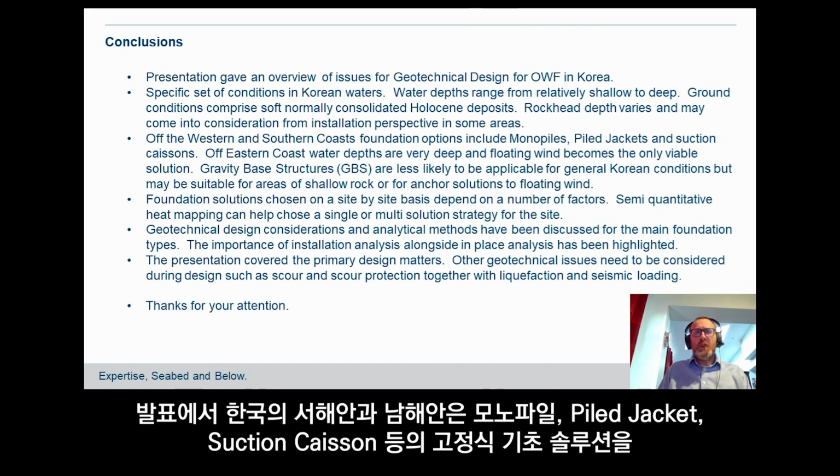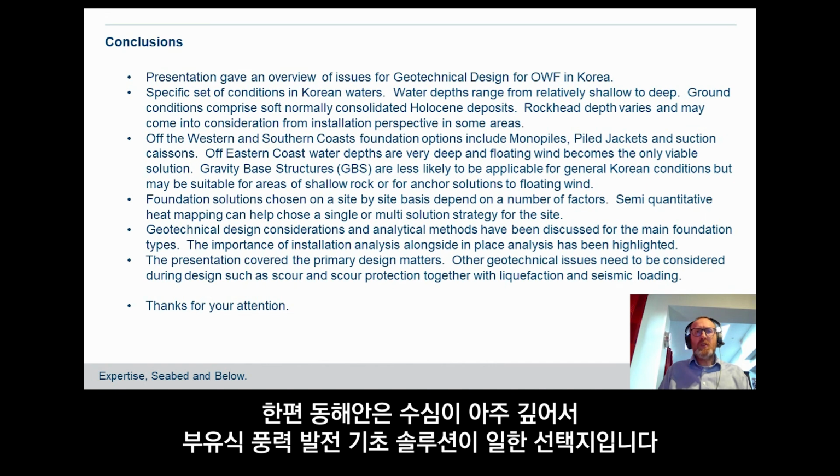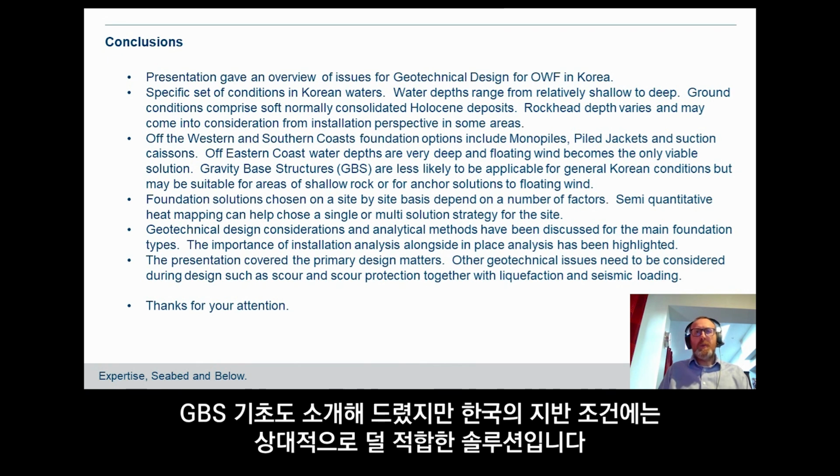From the presentation you can see that off the western and southern coasts, fixed foundation solutions such as monopiles, pile jackets and suction caissons could be potential options, whereas off the eastern coast where waters are very deep, then floating foundation solutions become the only real viable solutions. Gravity-based structures were discussed as well, although they're probably less likely to be applicable in the Korean conditions.